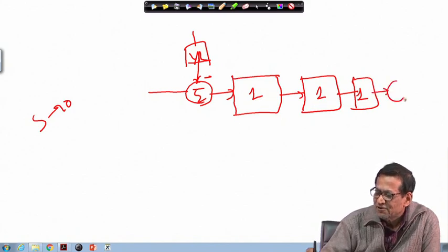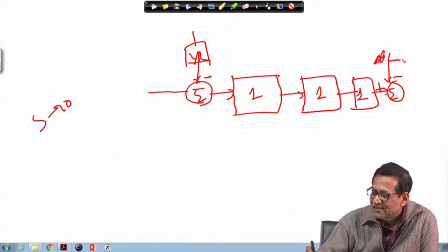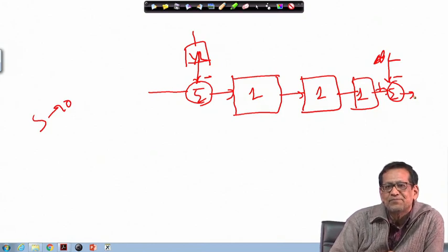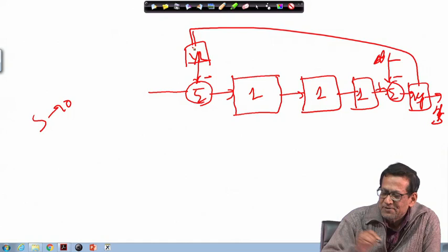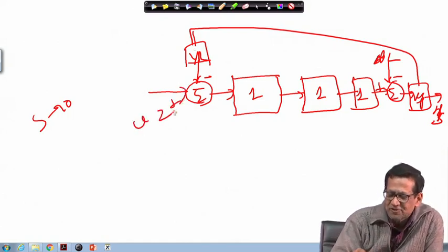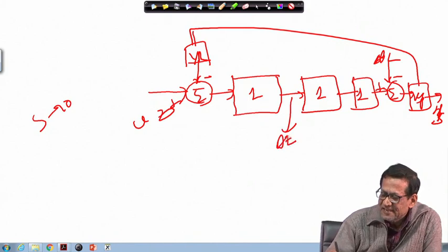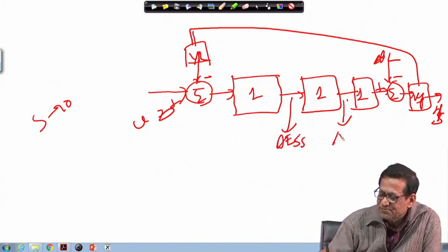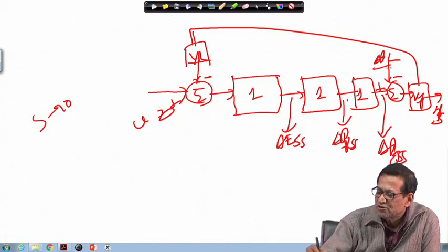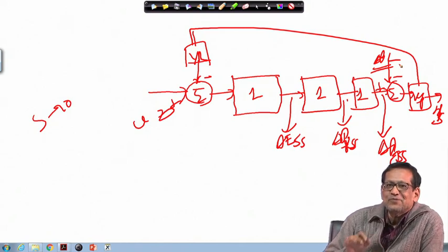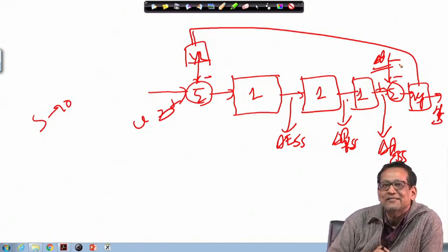Then this one is plus, this is minus, this is delta P_L, right, and here K_p upon 1 plus sT_p; put s is equal to 0 from that figure 11, then it will be simply K_p, and the output is delta f steady state. This is u is equal to 0, and this is actually delta E_ss. This is whatever the block has been split. So, delta P_V_ss, and this part is delta P_G_ss, and this is delta P_L, the load, right. So, in that block you put s is equal to 0. This will be a steady state block diagram.